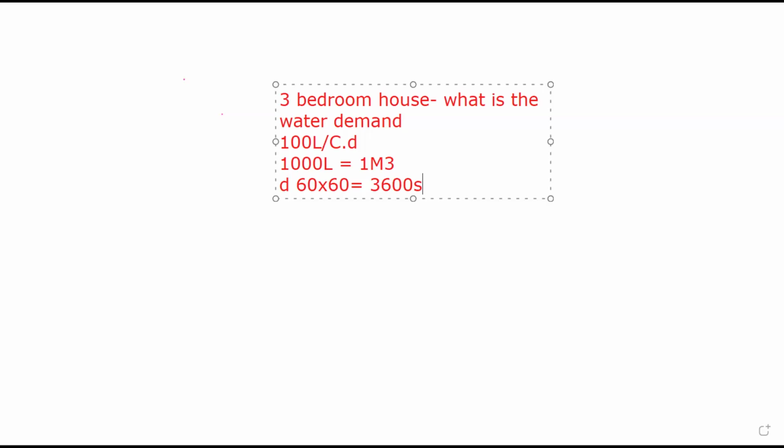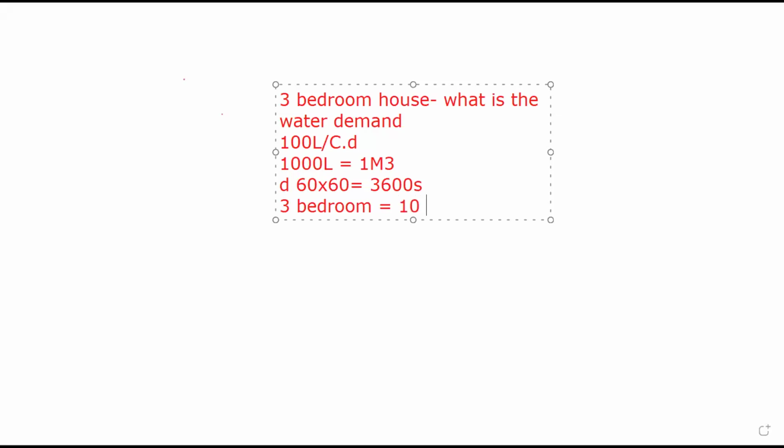So the next thing that needs to be established here now is the pipe size or the total water demand. So we will know, let's say that each 3-bedroom, how many people are in each 3-bedroom? Let's assume it's 8 people, or let's be lazy. Let's say 10 persons.